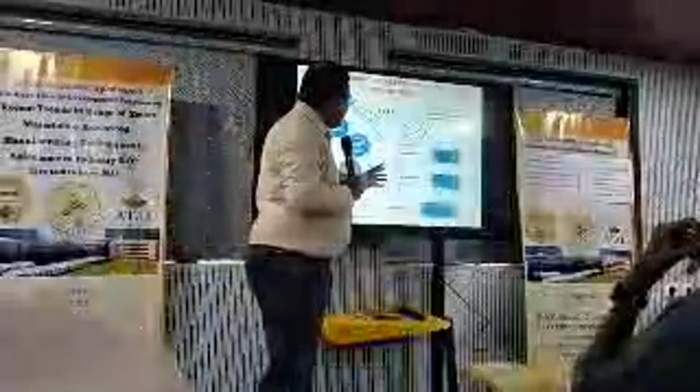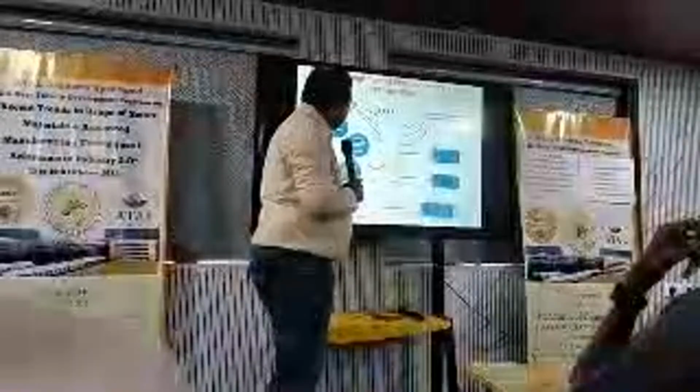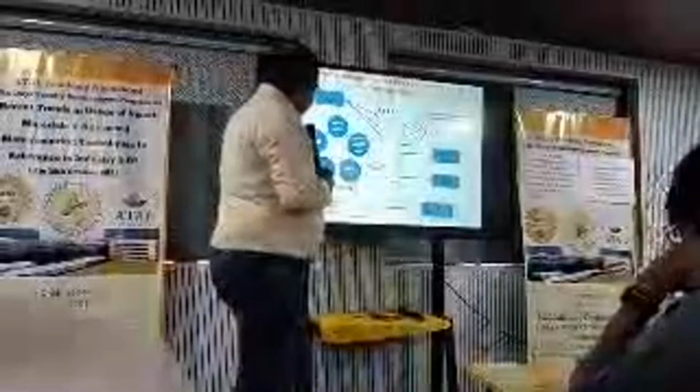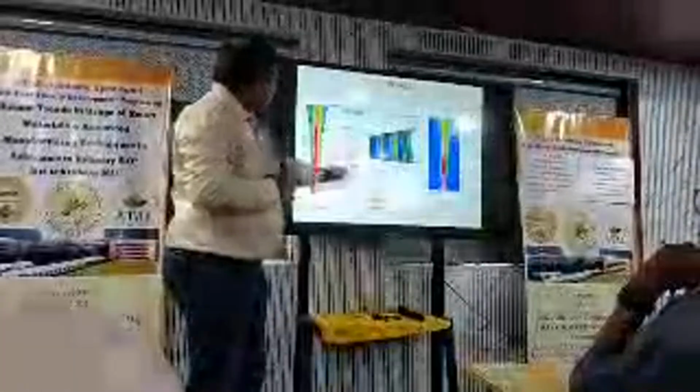Thermoacoustic silencer, first we have this transition noise. This is a mixing tube. These are the baffles. This is the exhaust gas which is transmitting to the final outlet. So we have to design the silencer such that both temperature as well as the sound energy we have to reduce. So this is the ANSYS model. Before doing that, we have to find out the dimensions, and we have to carry out the thermal analysis. That is, when the gas is flowing at different velocities, what is the temperature coming on to the structure that we have found out.